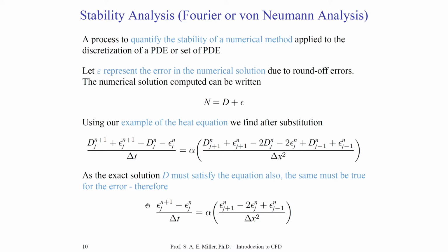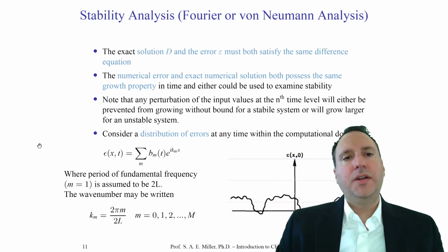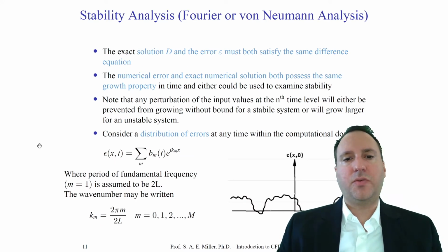So we can rewrite the original discretization as only one with the error on the equation itself. So here we have, instead of u, we would replace u with epsilon in this particular step. You can see by making this remarkable decision, replacing the equation itself with its particular error, we're able to assess the error in the same physical form as the original form.